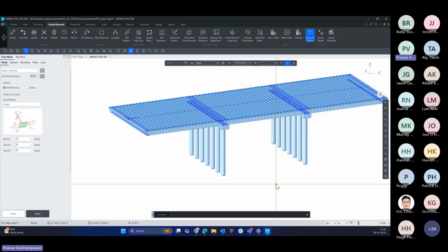We are going to create, so this group pile plugin will create pile cap and piles beneath a pier bottom. So just select the nodes following which we need to generate the respective structures. So select the bottom nodes of your structure using the single select and click on apply.